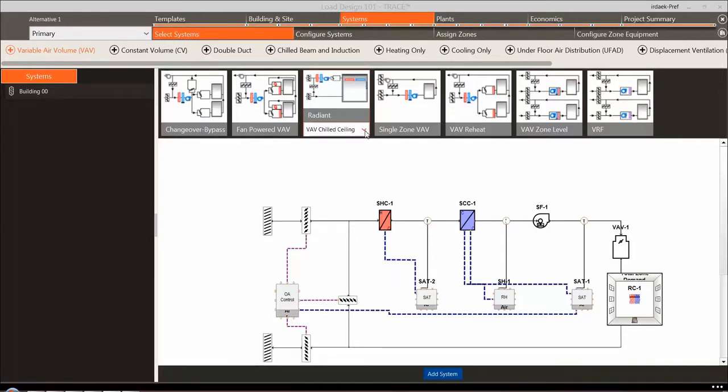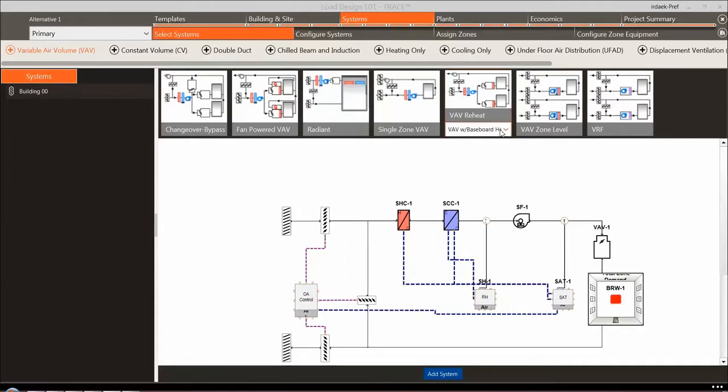In our example, we are modeling an office with several different space types, including a data center. We are going to select 3 different systems to condition this building. The offices are conditioned by a variable volume reheat system, so we will select the VAV system category and expand the VAV reheat system type to see the available choices. Let's select the variable volume reheat 30% min-flow default chilled water system.